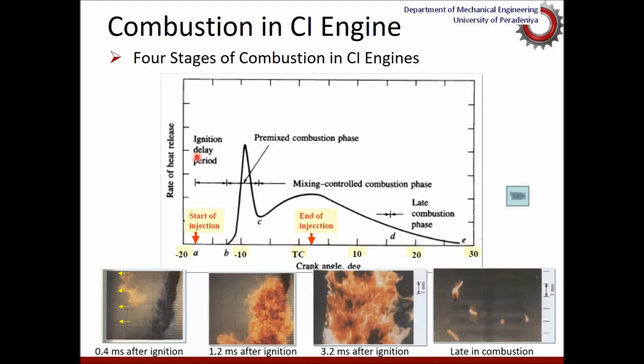So fuel and oxygen are needed for combustion. It takes a little bit of time to mix the droplets of fuel sprayed into the high pressure air, for the initiation of combustion. That is the ignition delay period.